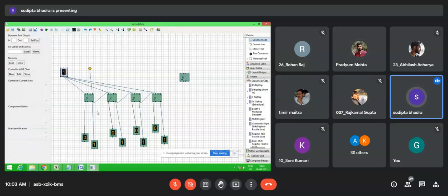So in the register the shifting happens, and after shifting, if I change it to 0, then again you can see from the first D flip-flop Q to the last D flip-flop Q, the 0 will be shifted. Once the shift has happened, the value will be fixed. But in case of a counter, let me stop the clock.